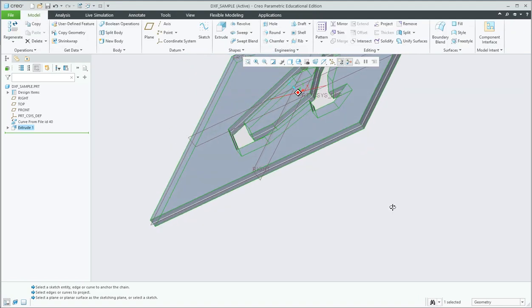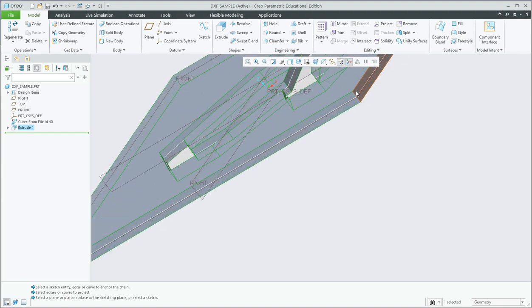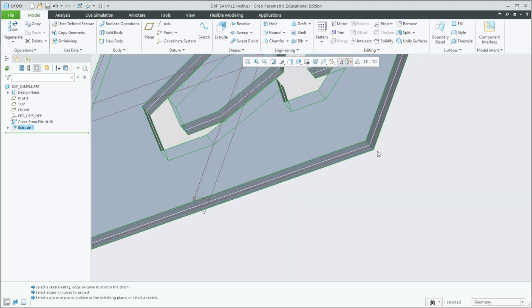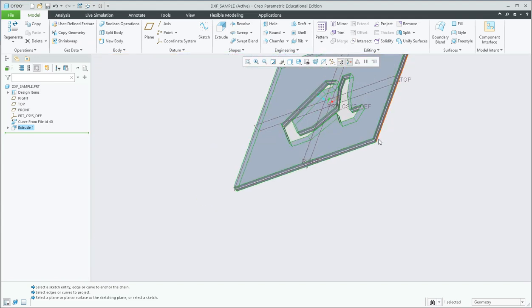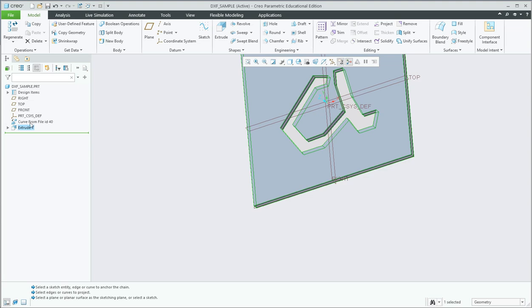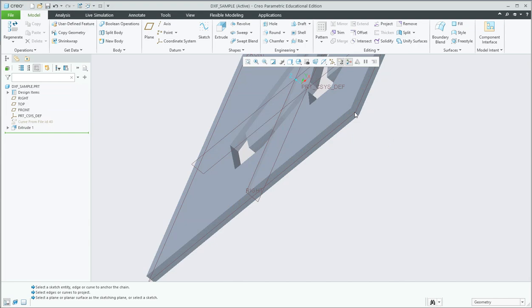And then there you go. So this is now a 1/8 inch extrusion on both sides. The total is 1/8. So it's splitting the extrusion above and below. Now you would still see the imported lines of your DXF. The best way to get rid of that line is to simply hide it. To hide it, you simply select your DXF curve on your file tree, and then select this Hide option, and then you now don't have any line on that one.